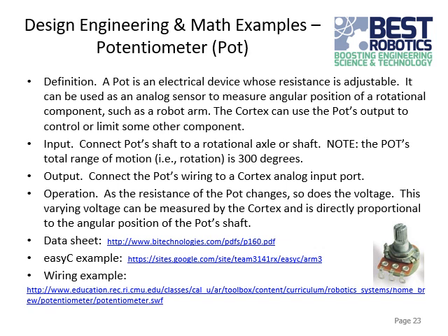That can be useful if you want to put in software limits of where it turns to. You can keep it from turning beyond a certain point just by reading that potentiometer. You can have the software cut the motors off if it goes too far.